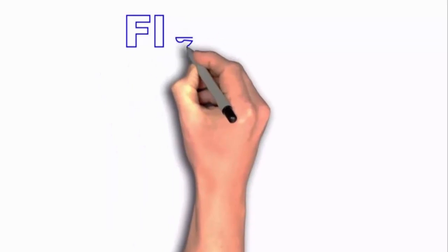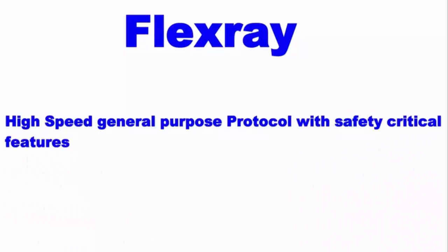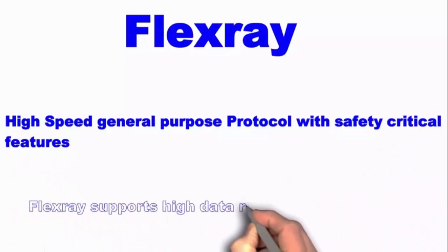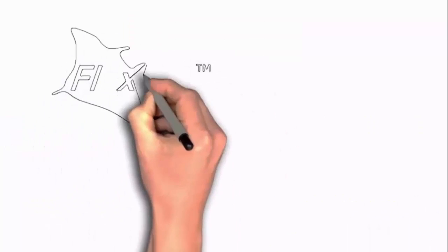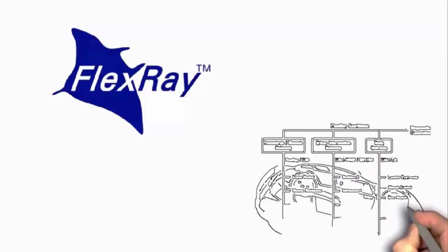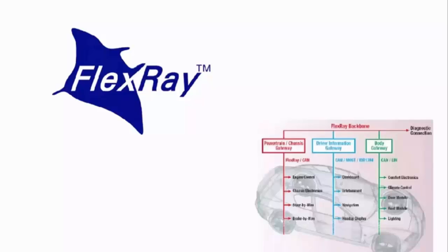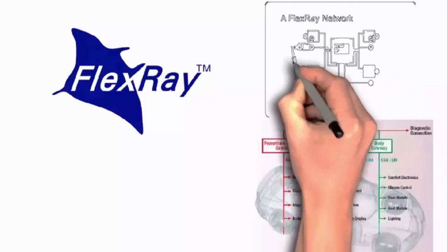We mentioned FlexRay earlier. FlexRay is a general-purpose high-speed protocol with safety-critical features. FlexRay supports a high data rate, up to 10 megabits per second, and is a serial communication technology used in particular for data communication in very safety-critical areas in modern vehicles. The bus operates on a time cycle, divided into two parts, the static segment and the dynamic segment.